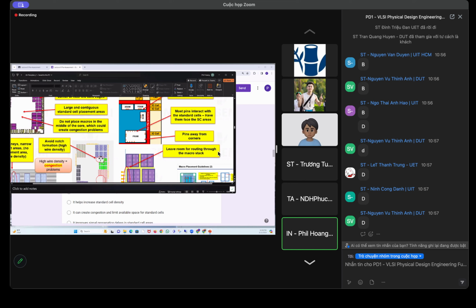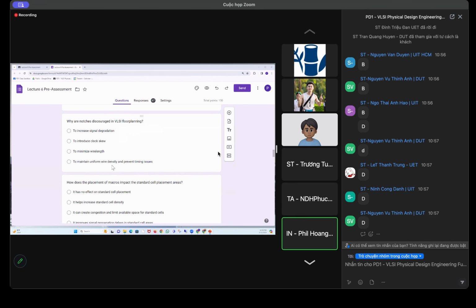Over here, now all of a sudden you have signals that need to escape from the memories, in addition to the signals in the standard cell areas. So all of a sudden, wire density over here is more than wire density over here. So cells have to be pushed out, critical paths are affected, and congestion appears here because you have more wires per unit area. So you want to discourage that. It still can be routable, but it will affect your overall quality.